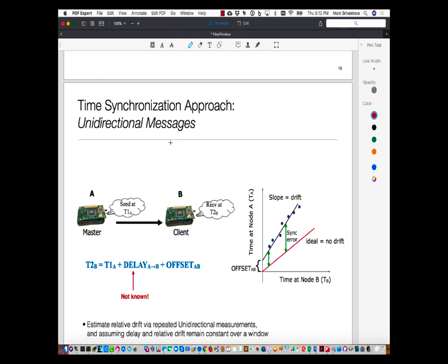But it depends upon how aggressive you want to be. In terms of achieving visual synchronization, namely 0.1 second kind of thing, I think that should be reasonably straightforward. If you want to minimize the time difference between the two pins, like if you were to observe at the pin level, then you may have to do the funkier stuff that I'm describing: some averaging, correct it over time. Don't just rely on a single thing. Basically, all I'm saying is that one measurement may not give you a good offset estimate, but multiple measurements averaged might.